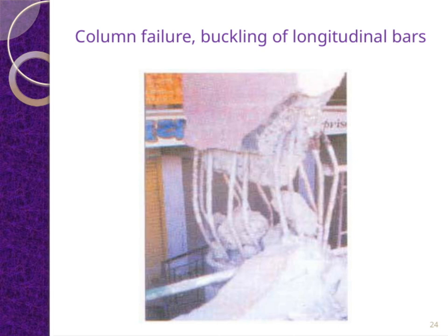By properly detailing the longitudinal bars, such as ensuring adequate confinement and proper spacing, we can help prevent buckling and improve the overall stability of our structures. This concept ties back to the overall theme of ensuring safety and durability in our structural designs.